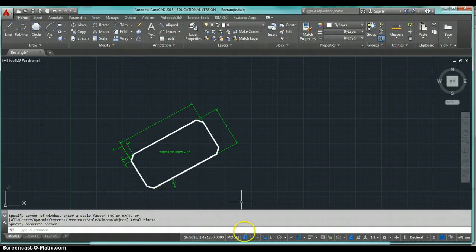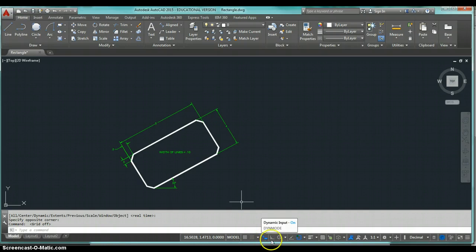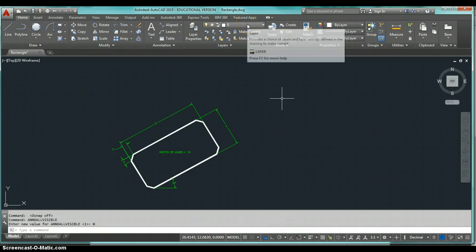So first thing, set our drawing aids. So I'm going to turn off my grid. Make sure that the only stuff that's turned on would be my dynamic input. For this, I don't even need object snaps turned on. So I'm just going to go ahead and turn those off so that they don't get in the way. And so hardware acceleration, dynamic input are the only things I have turned on. Step 2 is our current layer. So I've got my current layer as being 0.